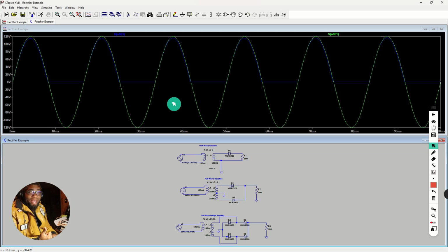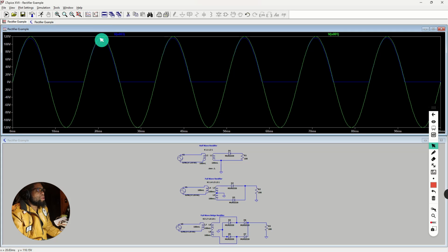Or you can tap something else. You can tap another winding on a transformer to use with a half-wave rectification if you're using something that's going to take a nominal amount of current. So it can be a very useful thing to do. Because as you can see, the circuitry is simple, and because the circuitry is simple, the cost is also less. So that is your half-wave rectifier, and Stan alluded to this earlier in that book.